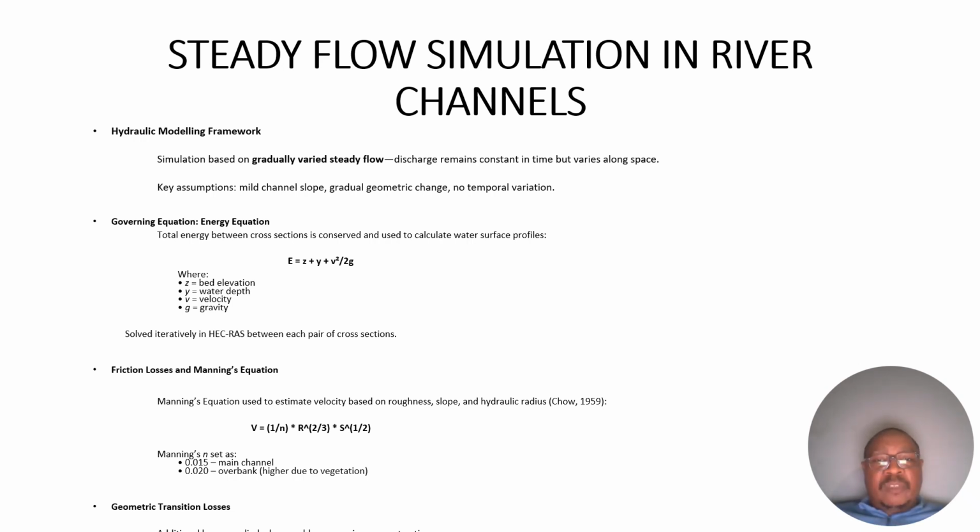Then if you look at the steady flow simulation in the river, of which this part is also detailed in the report, the hydraulic modeling framework simulates based on gradually varied steady flow. And then in terms of the equation that's been used for the total energy, where Z is the bed elevation, Y is the depth, V the velocity, and g the gravity.